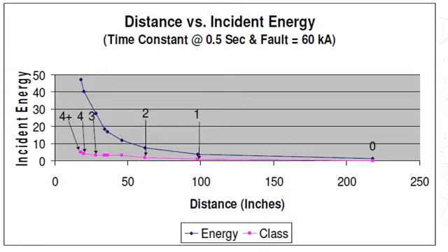Or the second case is that a person is qualified for both tasks, but initially the risk assessment identified that he will only perform condition monitoring at a working distance of 36 inches. During that, he identified a loose connection. He is qualified to perform the repair, but he is not wearing appropriate PPE to perform that task at a working distance of less than 36 inches.